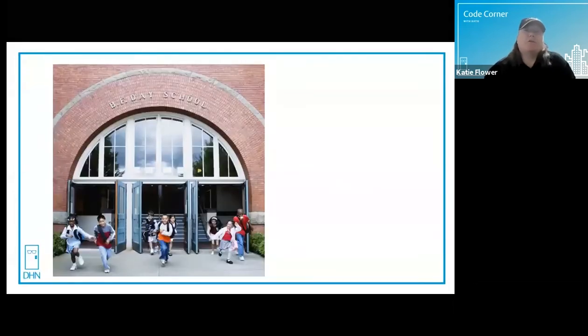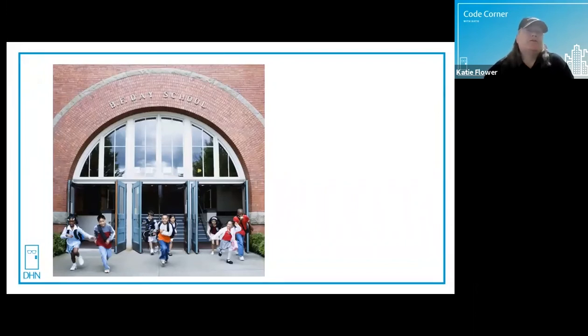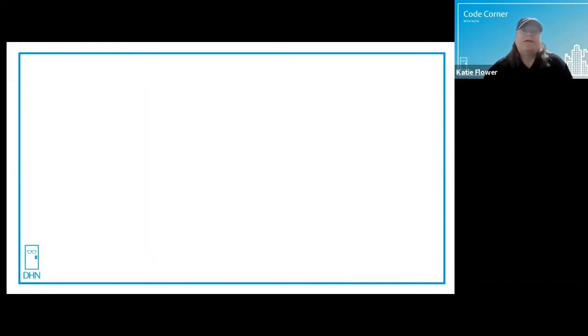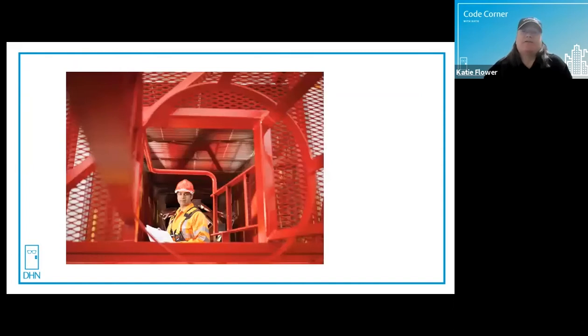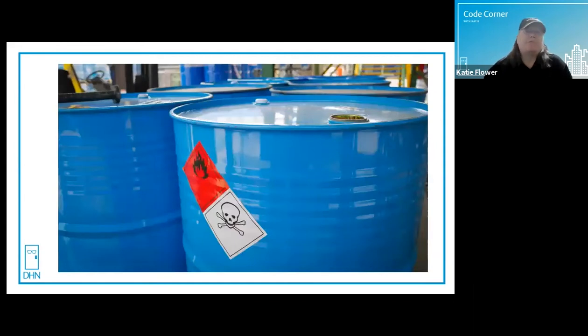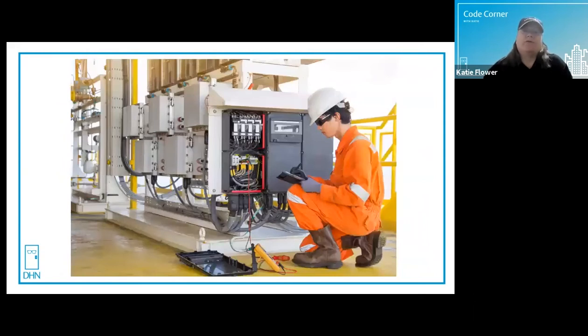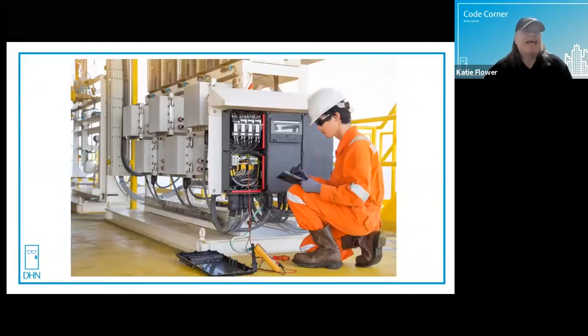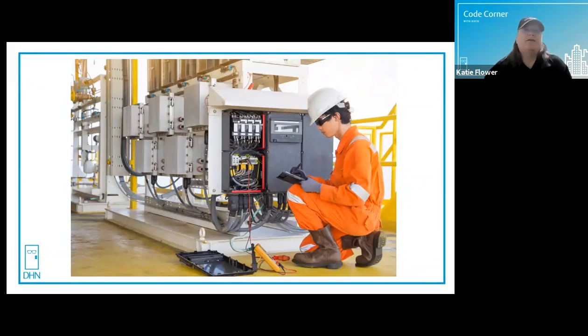Group E educational occupancies are K through 12, including nursery school and some daycare. And even though they have fire drills and are familiar with their surroundings, school-aged children are prone to panic, and they're considered a high-risk occupancy. Group H, high hazard, are not normally occupied spaces, but they do have materials that are capable of exploding or are highly flammable and are therefore high risk. Electrical rooms are also high risk with equipment 1200 amps or higher, and in some cases the benchmark is lower than this. You need to consult your local or state code.